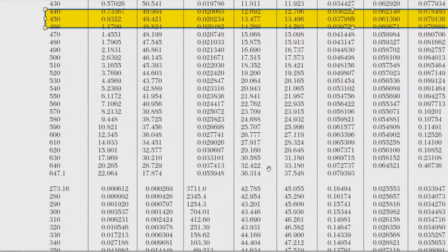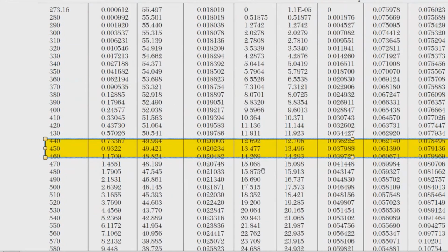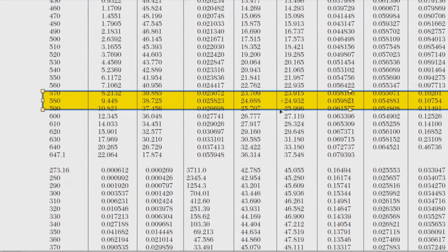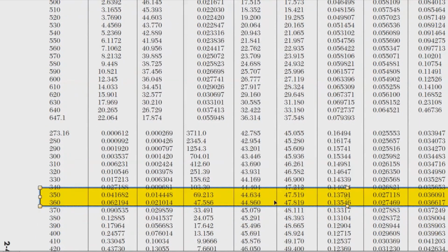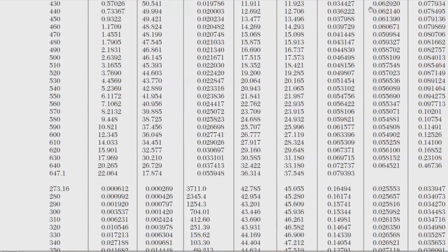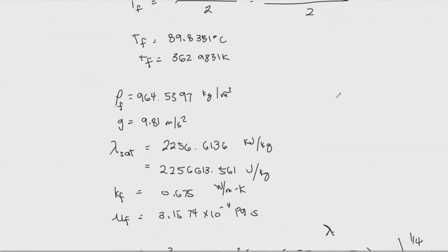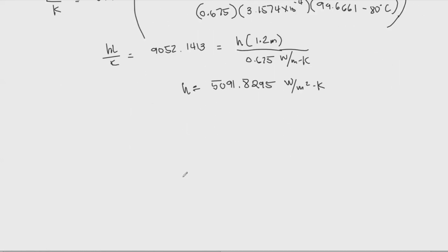And using the vapor phase only for the latent heat of condensation would also give you a wrong answer, since it's not pure steam, but it's a mixture of the two of them. So you need to subtract it. Okay, so if you're not getting the same answer for the latent heat, then probably you haven't subtracted the two values. So in this case, let's move on with our Q, since that's the one that we need.